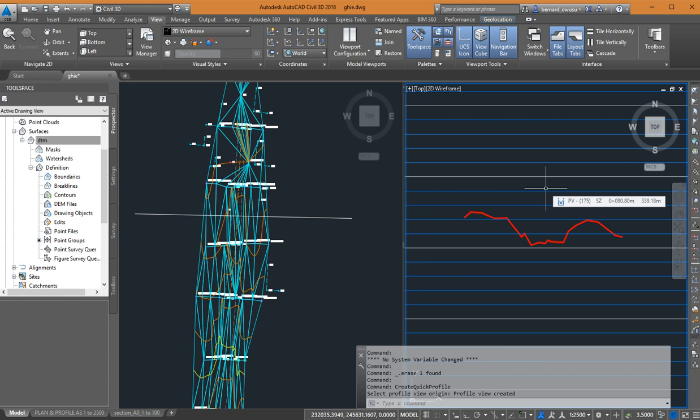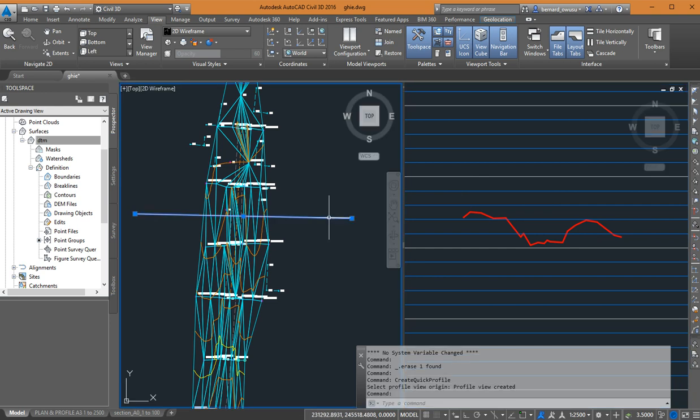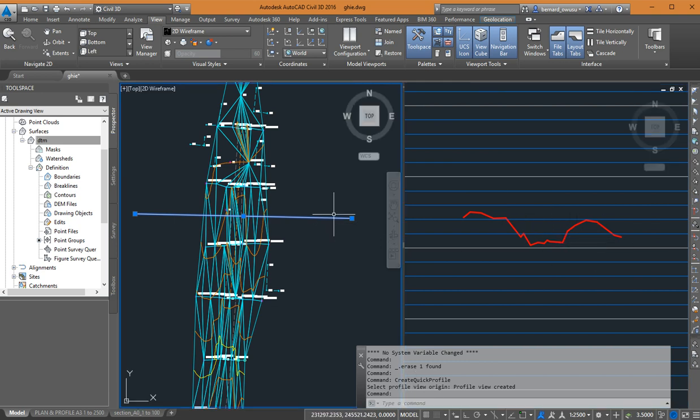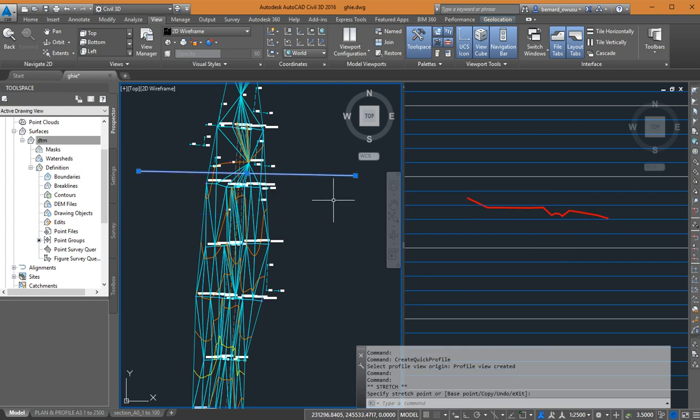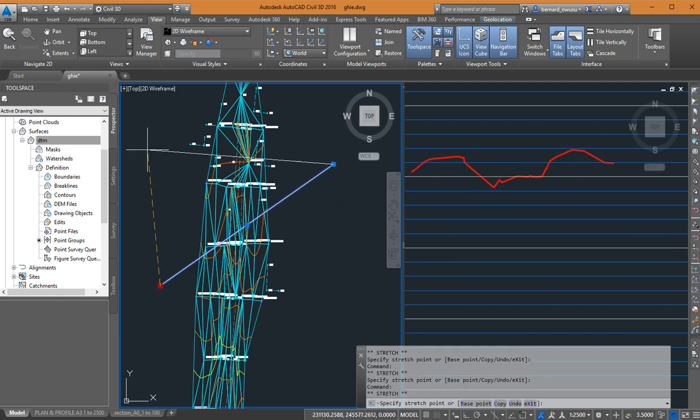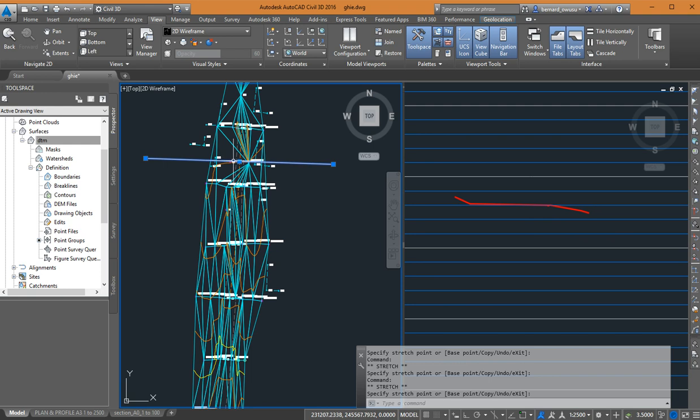Successful. Good. Now I want you to please observe something. You see that it is dynamic, in the sense that you should try to move the line. So zoom in to have your section on one side and your plan on one side. Now move the line and see what will happen to your cross section. What happens to it? It also changes. You understand? It changes, so just try to do something and see how it looks.